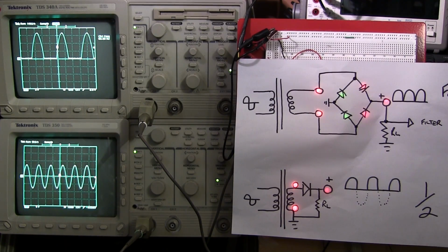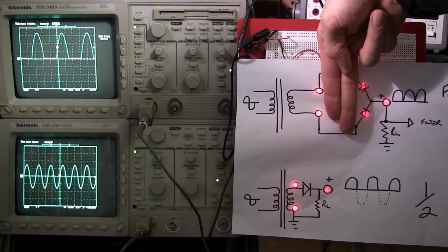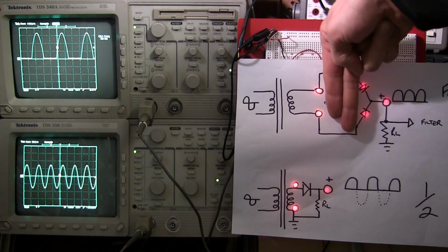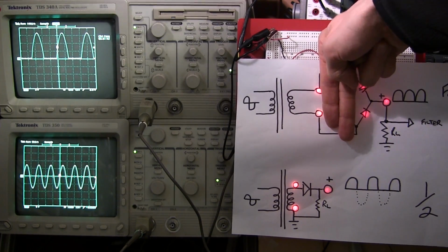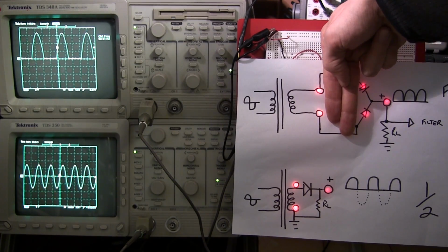Now, if we wanted to look at this as that third rectifier that I showed on the bottom, a full wave rectifier with a center tap, all you would basically do is just cover this up here, and you would have the center tap here, and the way that these diodes work would be the exact same function. They would just be going back and forth like that, and this would just be at a continual ground here for that full wave rectification there.